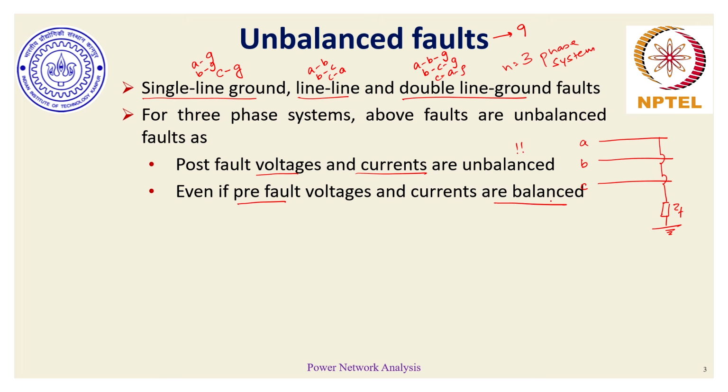Now, what do I mean by balanced or unbalanced? We have briefly talked about it in the basic circuit principles module, in which we say that in a balanced three-phase system, the voltage phasors for each of the phases have equal magnitudes and are 120 degrees spaced apart, and the corresponding orientation in which these three phasors of voltages can exist, we inherently associate with the positive sequence voltage, because coincidentally our three-phase synchronous generators inherently generate this three-phase positive sequence voltage.